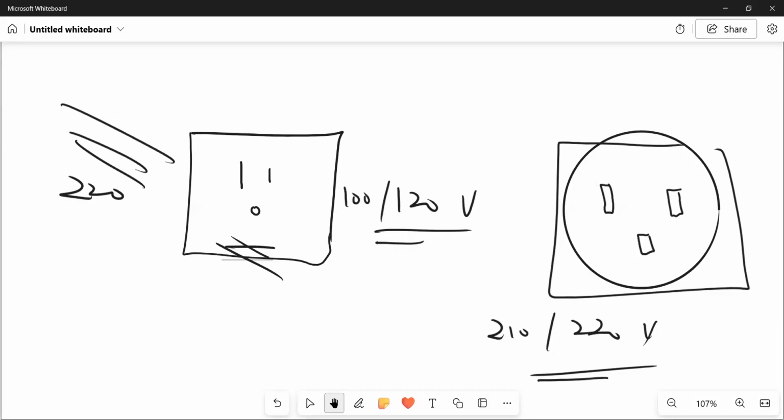And again, the same formula holds for AC power: P equals I squared R. That's why you don't want to let your currents be very large, because the power is going to be I squared R. When I is large, the wires you use in the system might very well have to be fatter.